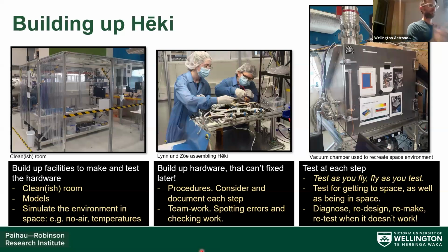It was very much a team effort. So you have people working together to check for errors and so on. And there's also a lot of testing which goes on. There's a nice little mantra there: test as you fly, fly as you test. So make sure when you're testing your hardware you're testing it in a way you intend to operate it once it's in space. And then once you're in space, don't be tempted to just change that little thing. You should do it like you tested.